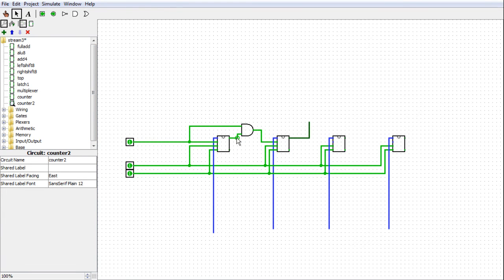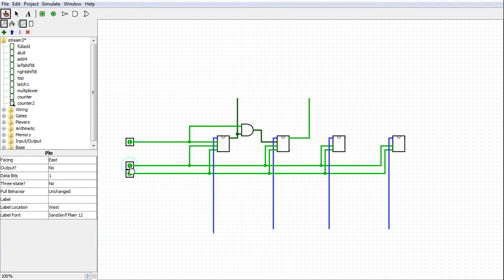Here we go. So this is data bit 0. This is data bit 1. Okay. Just had a weird brain episode again. They happen, you know. So 0, 1, 2, 3. Because this one is only going to toggle when this one's high, so it's only going to toggle half as fast as this one toggles, right? And that just keeps chaining up.